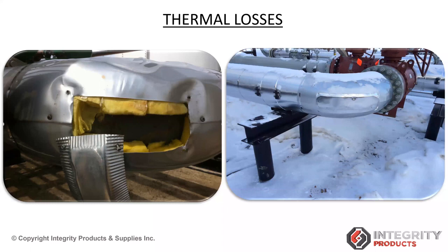So it's quite common practice across the industries, where they need to make an examination. They just make a window by cutting out the insulation. They take it out and they might place it on the platform or something. Or it might be a rainy day or a foggy day or something. The insulation is trapping the moisture.